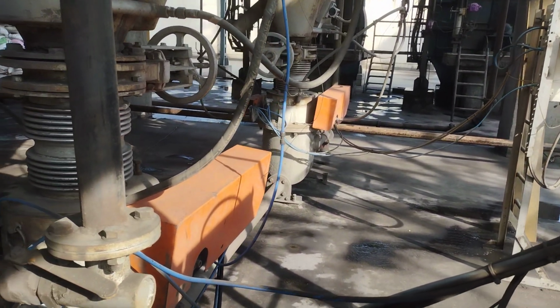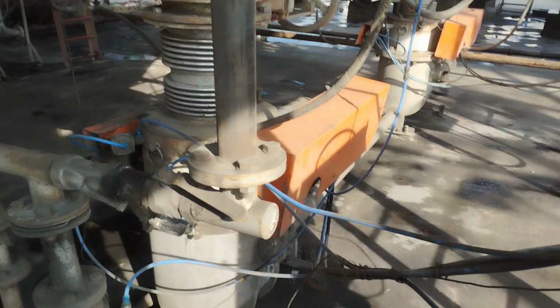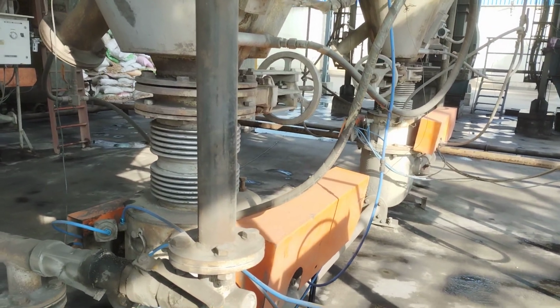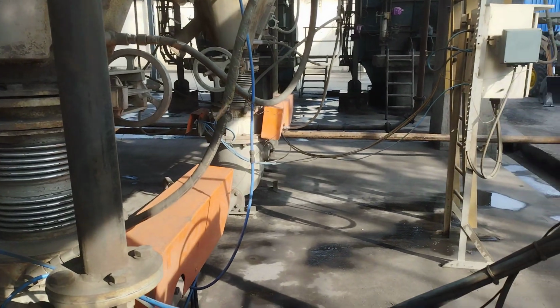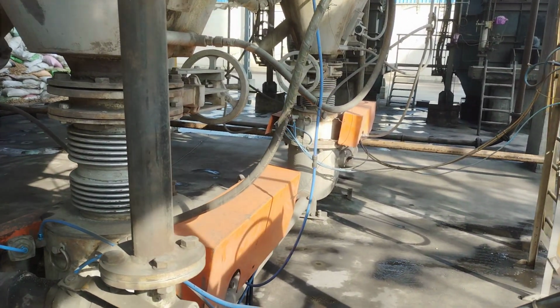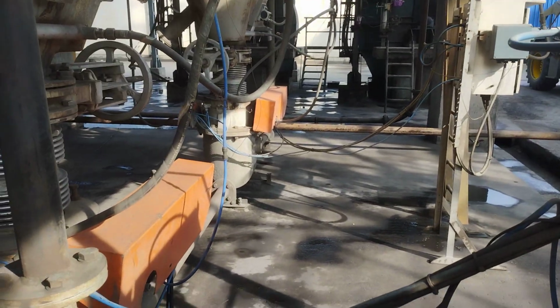This is the air preheater zone. The ash collection is very high, so the timing is 45 seconds. Inlet time 6 seconds, purging time 8 seconds. Purging start.